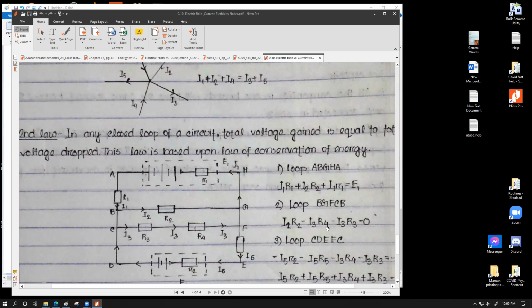But they are written in minus form because our considered loop direction was opposite to the considered current direction. Then we come to point C, good. From C to B there is no component, so there is no voltage drop. Now this is the total voltage drop that we have. Positive voltage drops for the same or matching direction, negative voltage drops for the opposite direction.